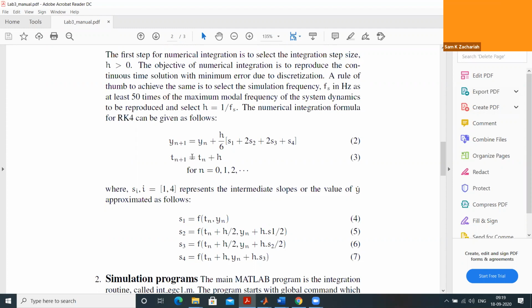So finally, everything has to be converted into a digital process. The continuous time process has to be converted into an equivalent digital process. This involves choosing the interval at which we discretize, or digitize, the process. When we do this, it is definitely an approximation. So the smaller the interval of discretization, the better the accuracy. So we have to select what the interval is.